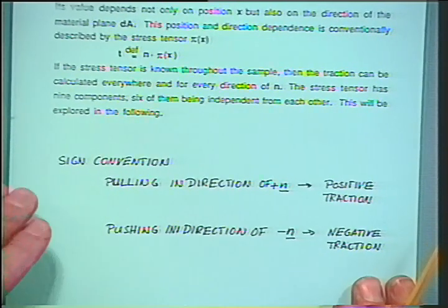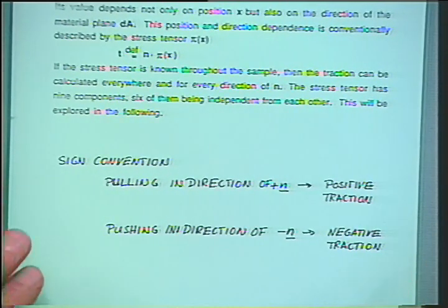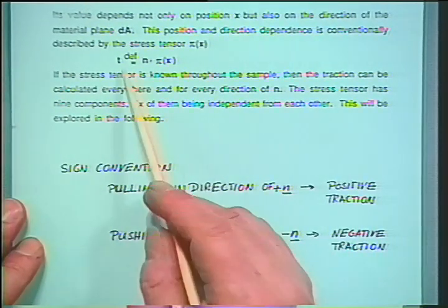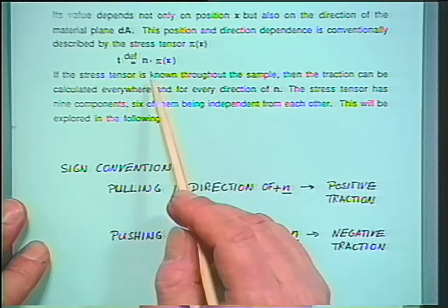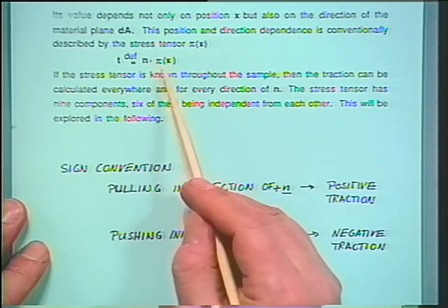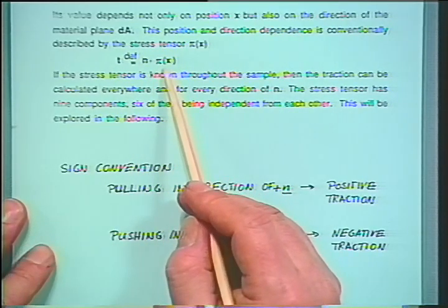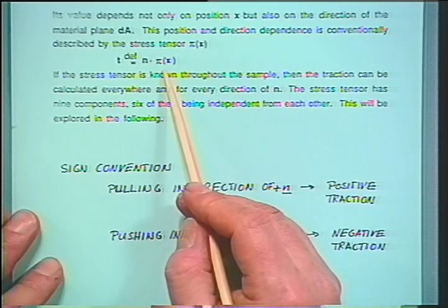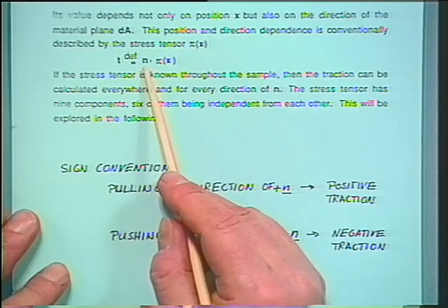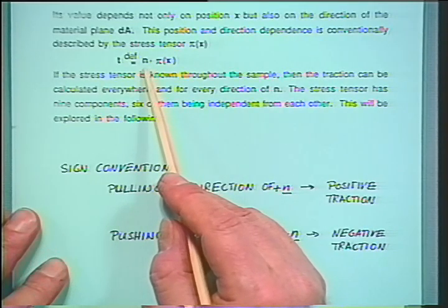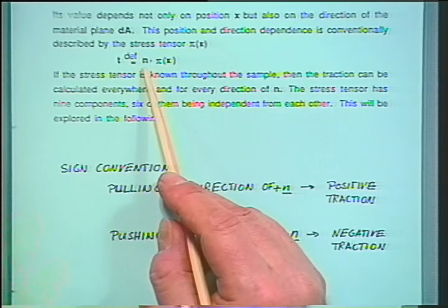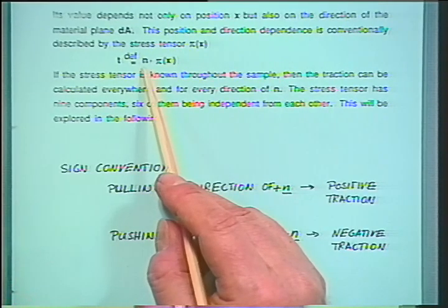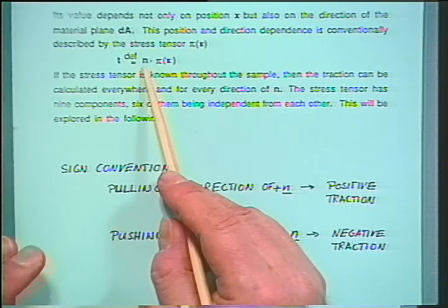And this traction now, if let's say we know all the forces locally, we have this transducer, we can measure everything, would be given by a tensor, the so-called stress tensor, which we have to define in greater detail, multiplied with the normal. The normal n is really defining our material area element dA.